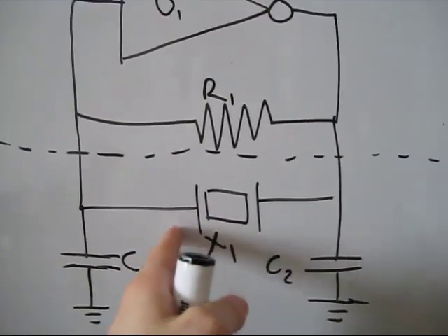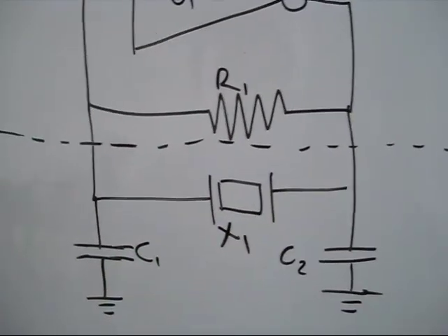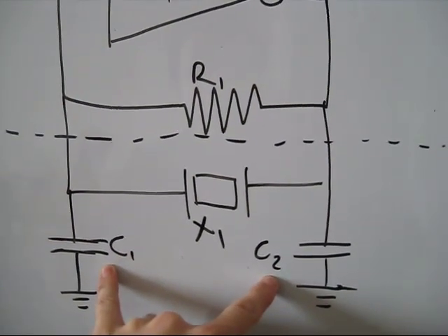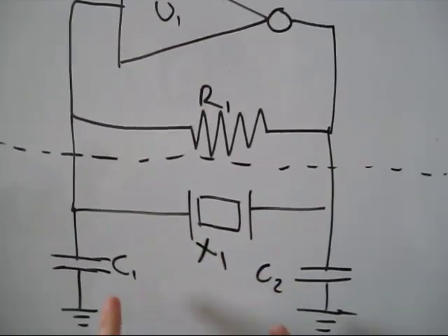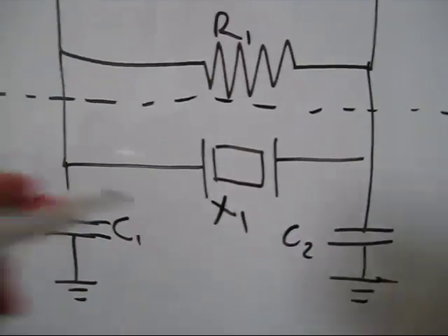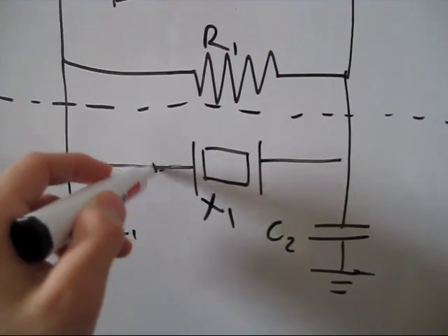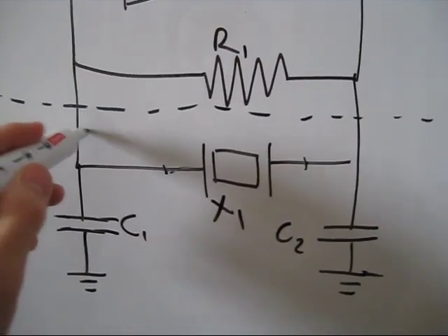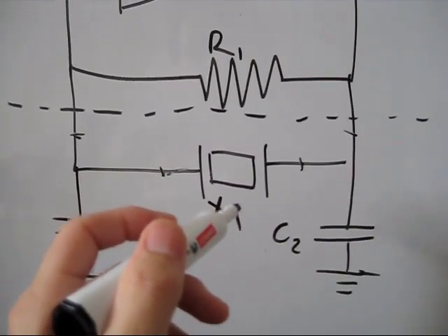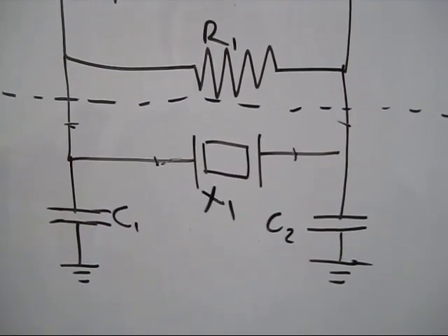Now, of course, if you're doing this for a microcontroller, and this is all internal, because we're assuming a microcontroller for a second here, when you buy the crystal, it says on the data sheet that it needs some load capacitance. These are your load capacitors here. If you look on Wikipedia, not only is there a derivation for how this whole thing works, which I don't want to get into because it's just a whole bunch of math, there's also an equation that'll show you what the actual load capacitance is. You have to take into account the stray capacitance from your PCB or your breadboard, the stray capacitance from the leads on your crystal, and the input capacitance from your microcontroller. You have to include all those factors. So if the crystal says I need 18 picofarads for my load capacitance, you can't just put 18 for your capacitors there. You need to do a little bit of math and see what the optimal value is.